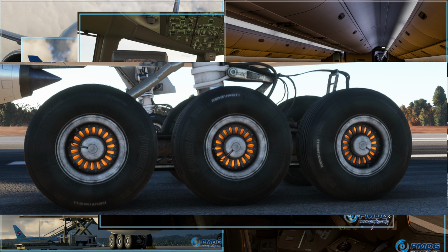However, note that maximum auto braking during the RTO scenario is not as much as maximum manual braking when the pedals are pressed completely to the front, but it is recommended to use the RTO auto brakes nonetheless and not override it manually, because though the RTO auto brakes don't apply the absolute maximum amount of braking, they are usually going to be more effective than a pilot braking, because the pilot